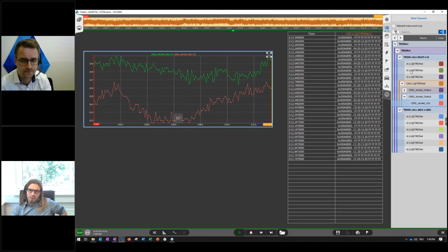Exactly. Which is awesome. And the data size of your data file will be significantly reduced as you can only store the raw CAN data stream, and also the CPU load for decoding the CAN message will be significantly reduced. So the CPU load will be much lower during the measurement. Perfect. That's nice to hear.